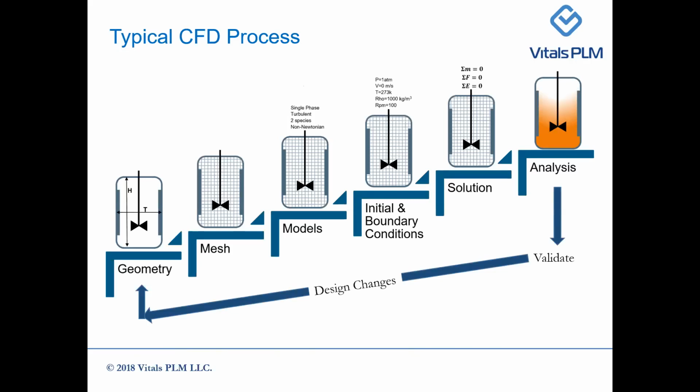Typical CFD process includes, once we formulate the problem statement, geometry modeling, mesh generation, identifying the physics, whether it's single phase, multi-phase, turbulent, laminar, non-Newtonian, Newtonian, combustion, and then the initial and boundary conditions.